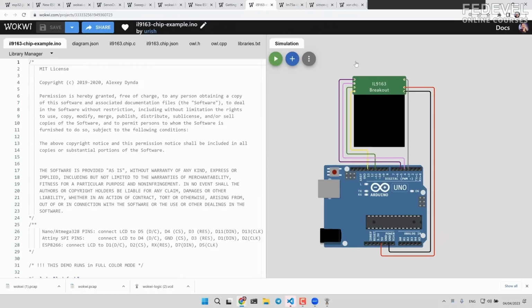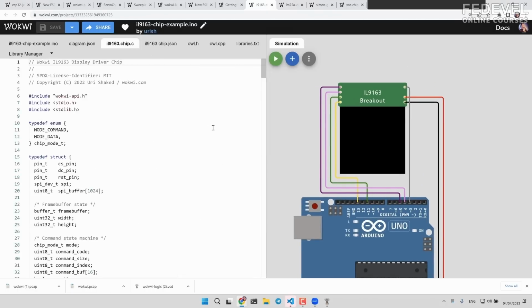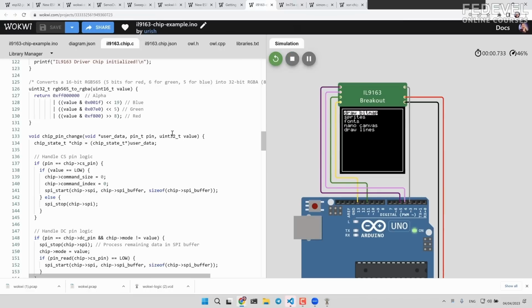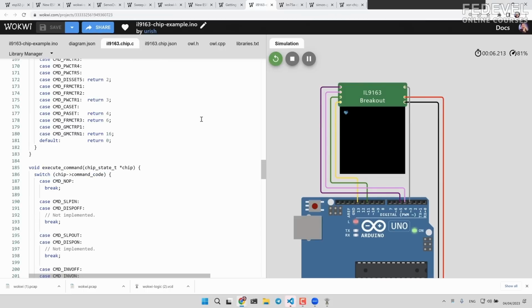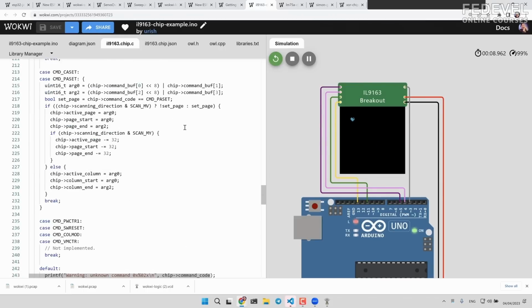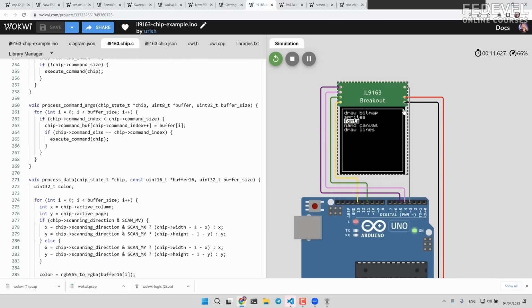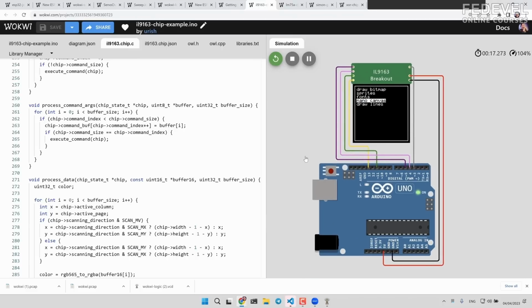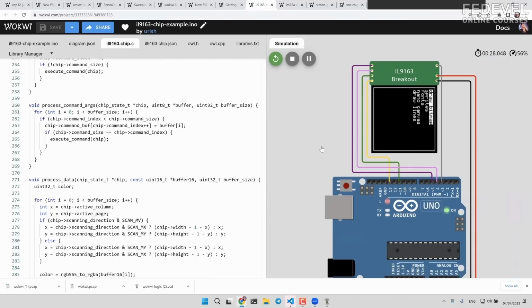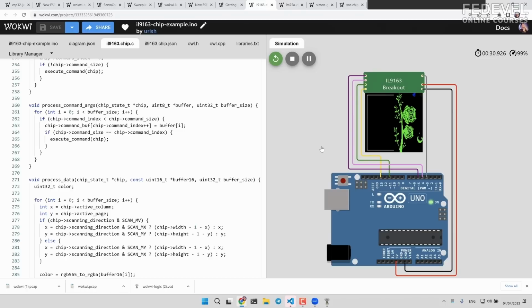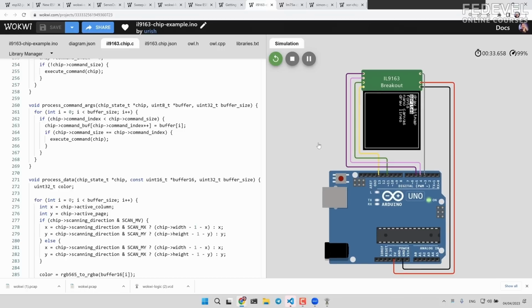I think this is one good example, because the chip actually implements a display. It's a display board that we don't have in Wokwi, but this was one of the more complex demos I created with the chips. It implements this display chip controller, and it lets you see on your screen whatever is sent from the Arduino. So if there is some unique LCD that you don't have yet in Wokwi, you can implement it as a custom chip. And you even have these existing examples. That's how the person who created the ePaper display did it, just creating this custom chip.